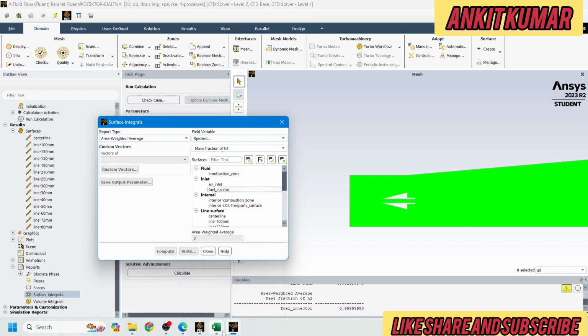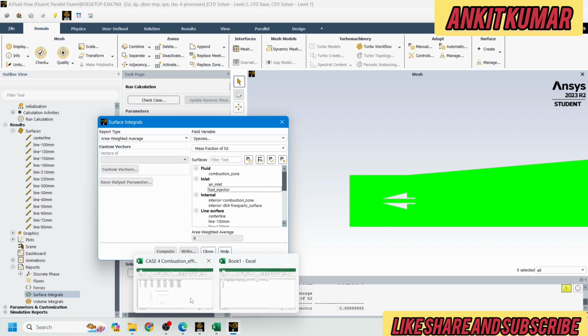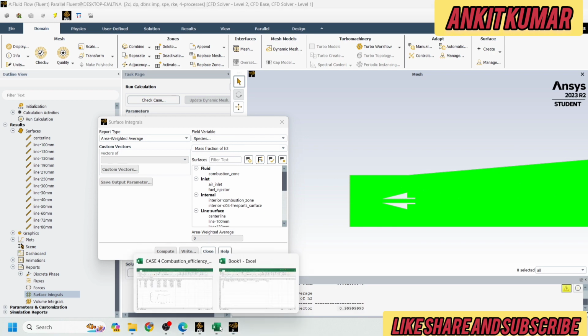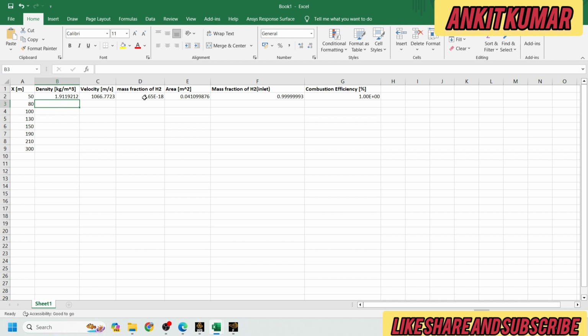One more thing I need to tell you about combustion efficiency. The length of the combustor is 300 mm and the fuel is injecting from a length of 67 mm, so here is our fuel injector at a distance of something around 67. Since we have taken the line at 50 mm, the hydrogen here is zero, negligible. Here we can see the value: the hydrogen available at 50 mm is very small, 8.65 times 10 to the power minus 18, no hydrogen is available here. So that's why combustion efficiency is coming as 1, since with no hydrogen, 1 minus YH2 divided by YH2 inlet came to 1.